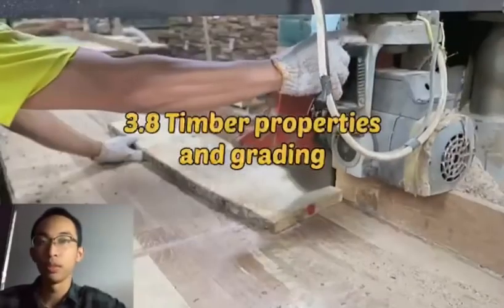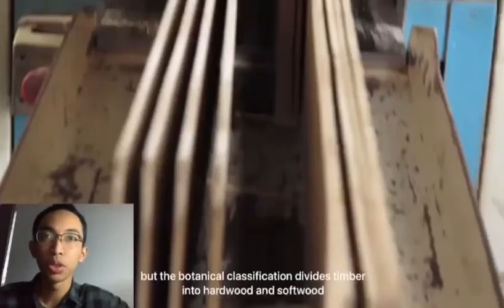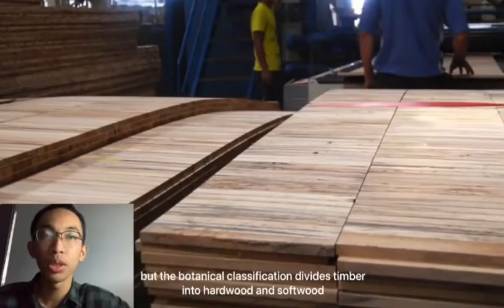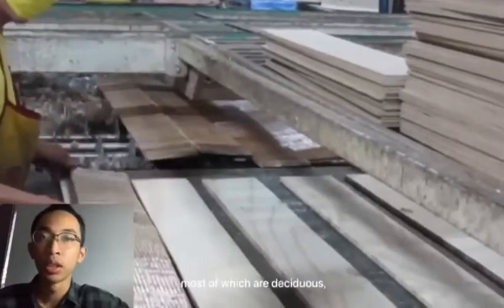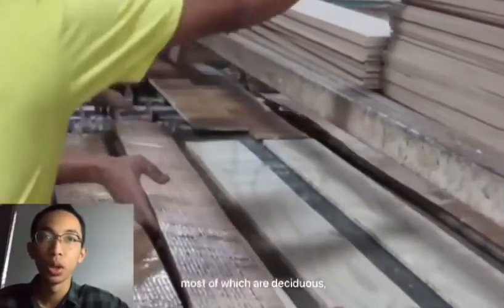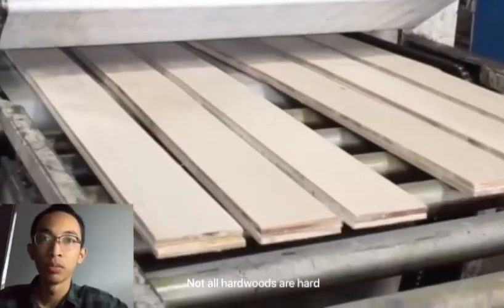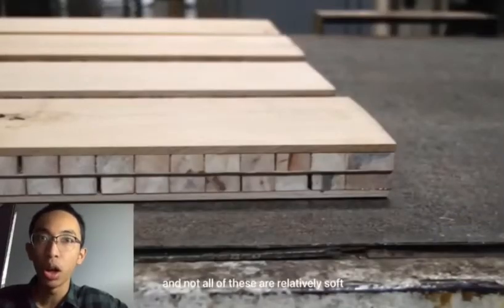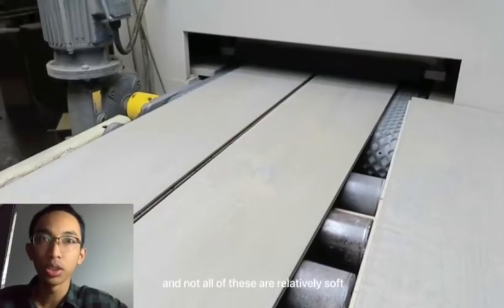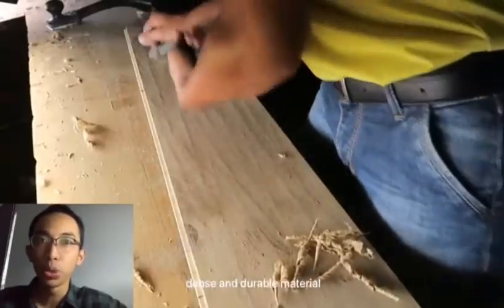Timber properties and grading. Timber varies across thousands of different tree species, but the botanical classification divides timber into hardwood and softwood. Hardwoods are from broadleaf trees, most of which are deciduous, holly being an exception. Not all hardwoods are hard. Balsa is an example of a soft hardwood. Softwoods are from coniferous trees, and not all of these are readily soft. For example, yew is a very strong, dense, and durable material.